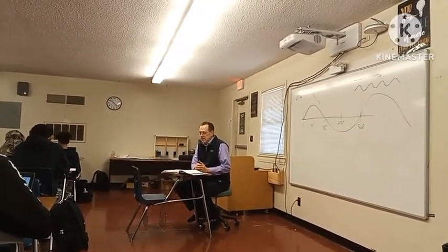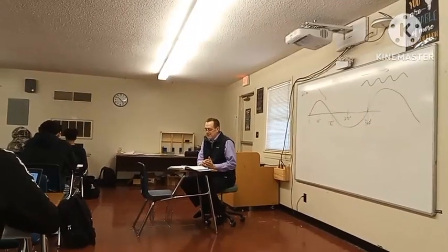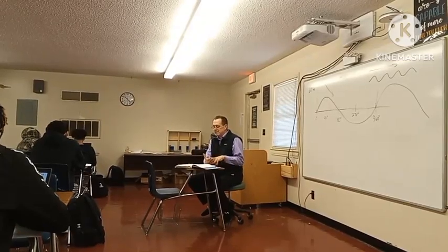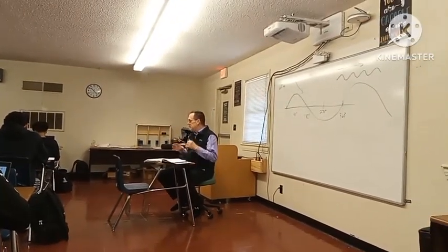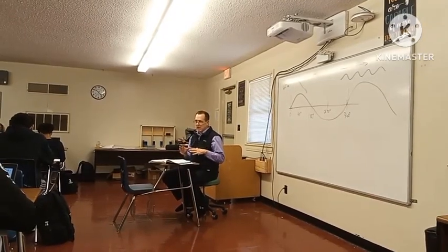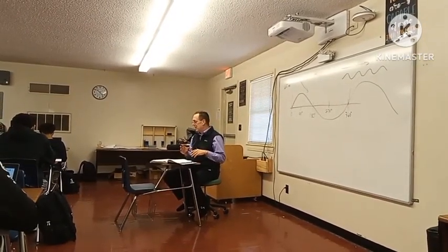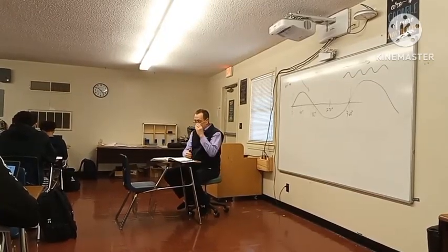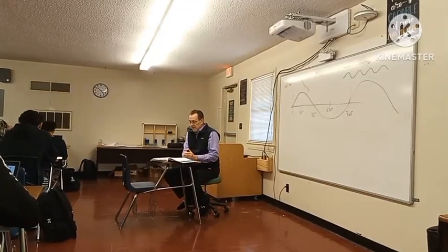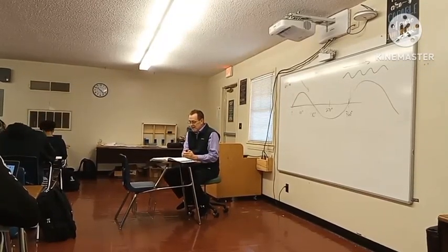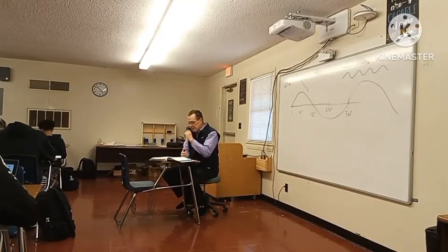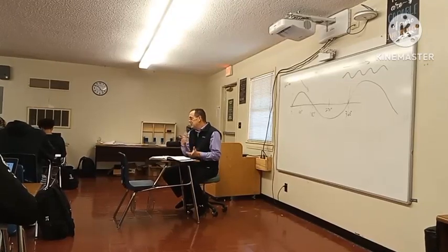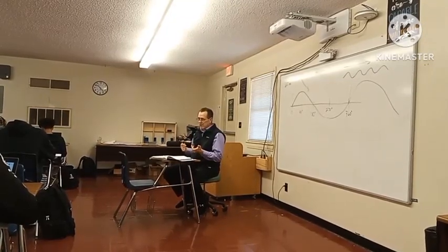AC voltages are usually expressed as RMS values. That's what I was just talking about. So you're going to have your 120, 208, 240, 277, your 480. All of those are your RMS, or your root mean square, values. All right? The peak voltage differs from that. For example, the peak value of 120 volts is actually 120 times 1.414. And that equals what? 170 volts, right?